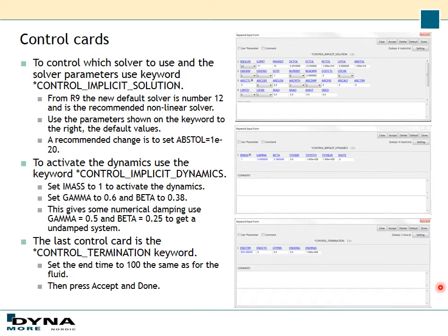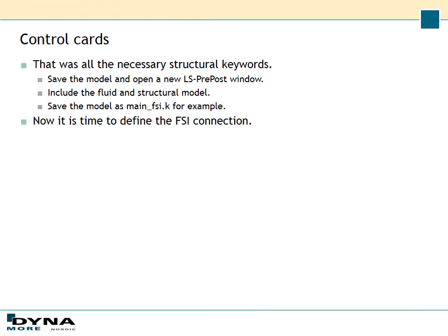And the last control keyword that we're going to use is control termination, which controls the end time of the simulation for the structural part. So set it to 100, which is the same as for the fluid. That was all the necessary structural keywords.